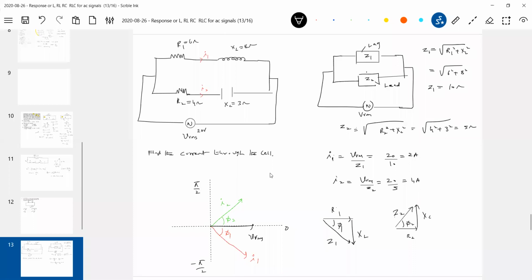Shall I bring it also in the second, third quadrant? No, try to look here. What is the reference? This is the reference. I took the source as reference, the phase of this as 0. Compared to applied voltage, the current in an RL circuit lags. Agreed? Compared to applied voltage, this is 0 phase. I took this as reference.